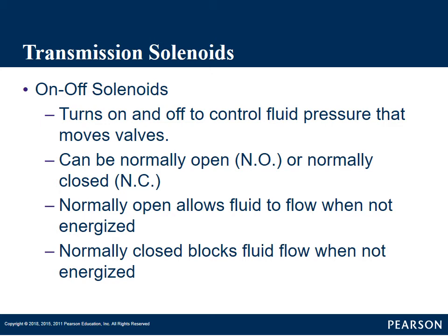When they want to energize the solenoid, the computer applies a ground path, current is able to flow, energizes the coils, and creates a magnetic field. When they de-energize it, they're releasing the ground path, and there's no path for that current. No current flow means no magnetic field.